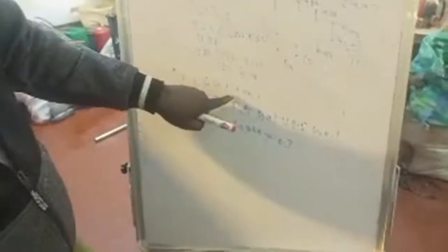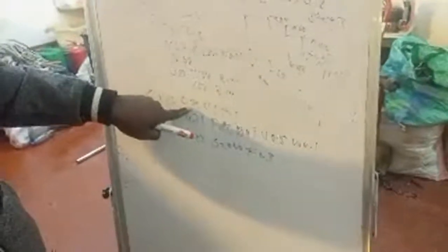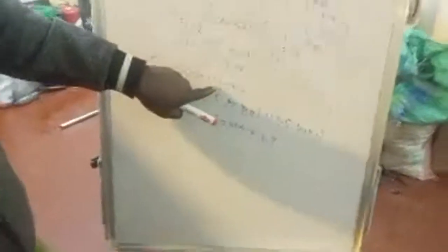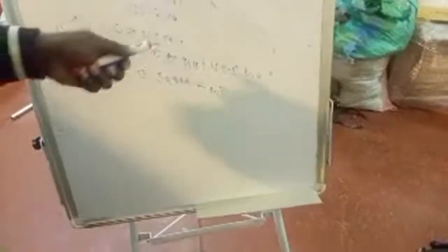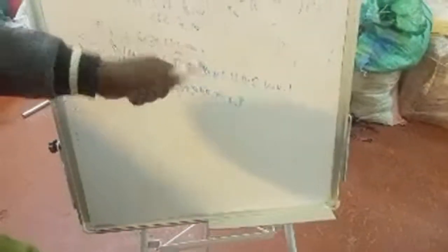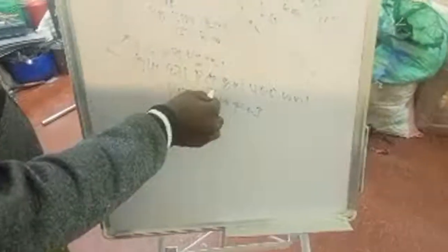And again, what does it mean by using G71? I've said G71 is stock removal along Z-axis, and then U1 is the roughing in-feed. Then R1 is retraction from the workpiece. P denotes where you are starting to cut.